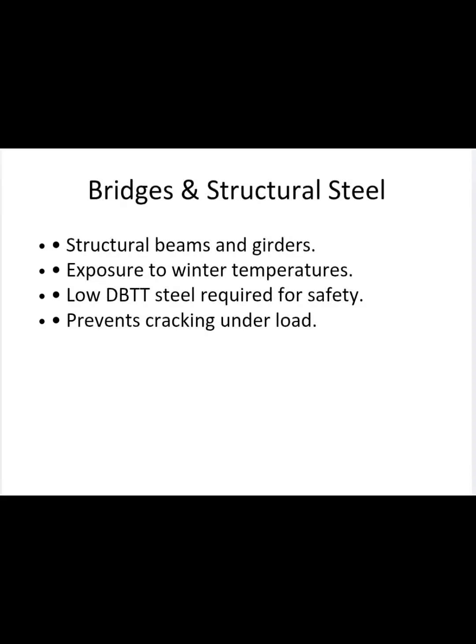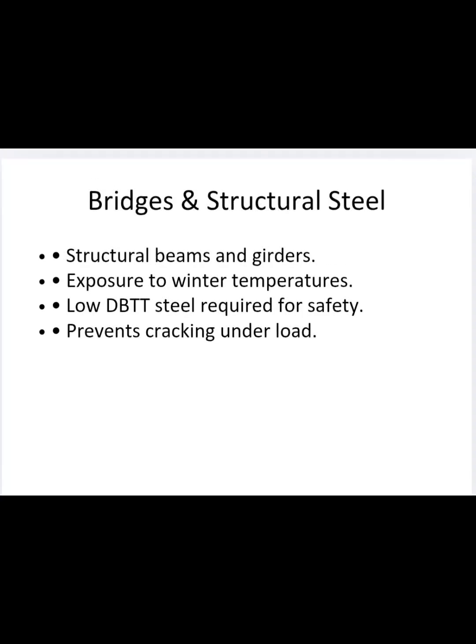If the steel used in these constructions has a high DBTT, it may become brittle during cold weather and may fail suddenly. So we use low DBTT steel, which can prevent cracking under load.